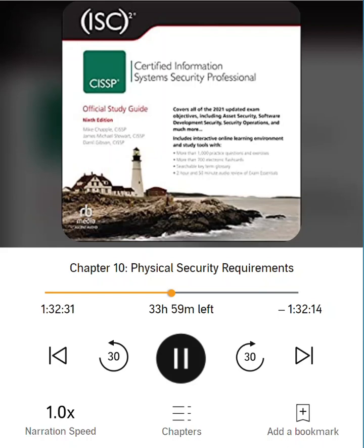Rate of rise detection systems trigger suppression when the speed at which the temperature changes reaches a specific level. These are often digital temperature measuring devices which can be fooled by HVAC heating during winter months and thus are not widely deployed. Flame-actuated systems trigger suppression based on the infrared energy of flames. This mechanism is fast and reliable, but often fairly expensive. Thus, it is often only used in high-risk environments.